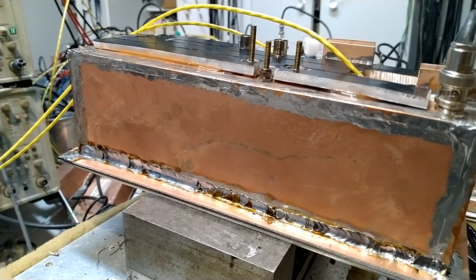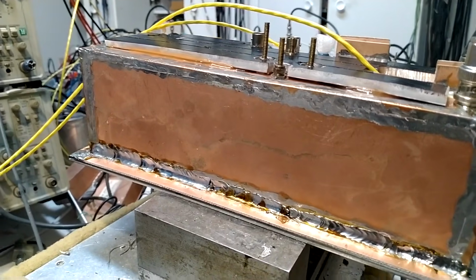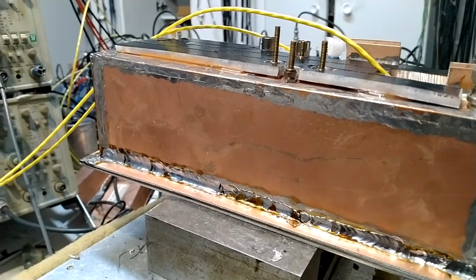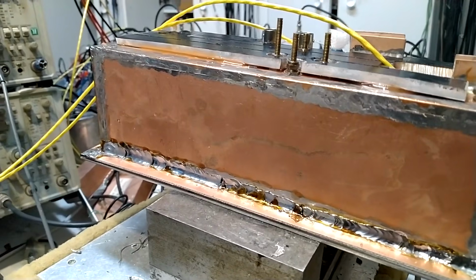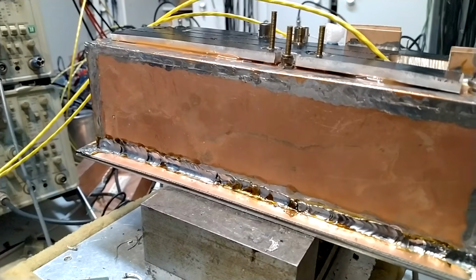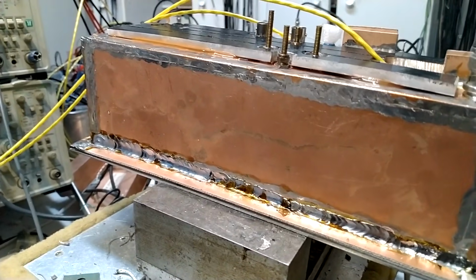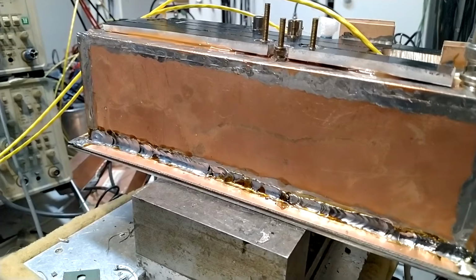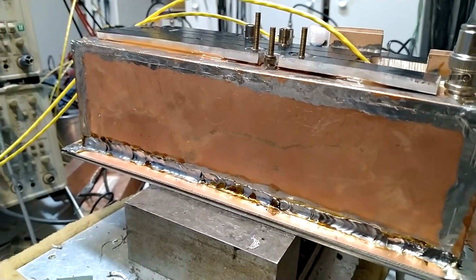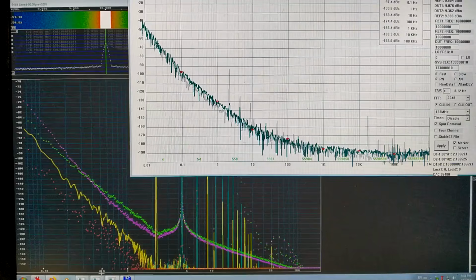If temperature differences are small enough, air will circulate inside the box with laminar flow. But if temperature differences come over some certain point, the circulation will be turbulent. It could even be oscillatory, as we have seen earlier in this video. So I will see what happens when the cotton is no longer inside. The problem with chaotic air circulation inside the box is solved. Just make the temperature even on the top of the box.